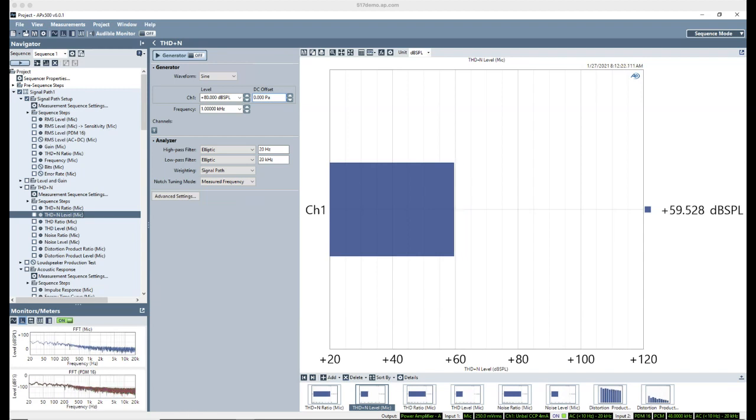Oh, and then I think the last question is, what about the distortion of the loudspeaker, especially when driven high? So it all depends on what you're measuring. You'll notice that the measurements that I've demonstrated today are sensitivity, so the output of the transducer for a given sound pressure level input, frequency response, and phase response. Those measurements are not affected by the distortion of the loudspeaker.